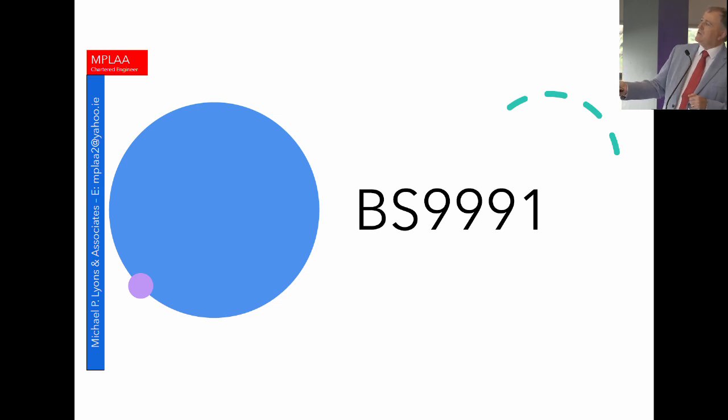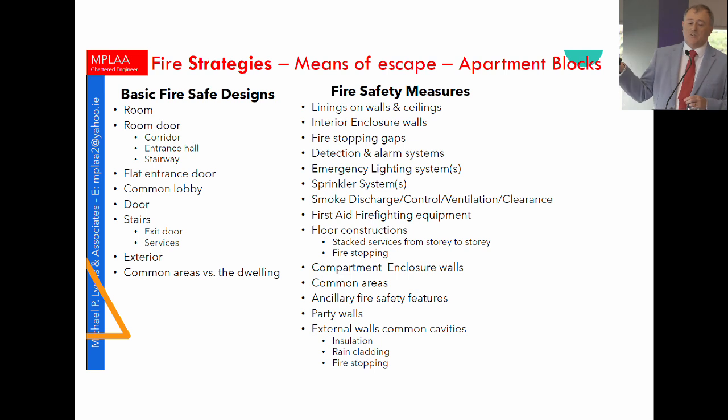The fire safety strategies are all very, very similar. Fire doors, flat entrance door, common lobbies, stairs, exterior fire safety. I would actually venture to say that TGD B 2024 has got provisions which are a little bit easier to use. The 10 meters goes up to 11 meters. The external escape stairs goes from 6 meters up to 11 meters. So there's a whole load of reasons, and open plan flats, domestic sprinklers. The one thing I keep saying, and somebody might listen at some stage, is it doesn't mention water mist systems. It really does. The next version of it needs to really mention water mist systems.